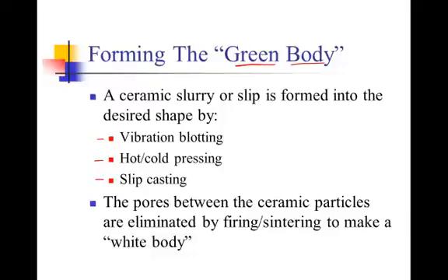And the method that we use will control the porosity, the flaws in the final product, and that will control the strength, and it will control the possible amount of opacity that we'll have in the final ceramic. And if we have a lot of porosity, we will need to try to eliminate that. If you have a lot of porosity, it may be impossible to fully eliminate it, and you'll end up with a porous white body.